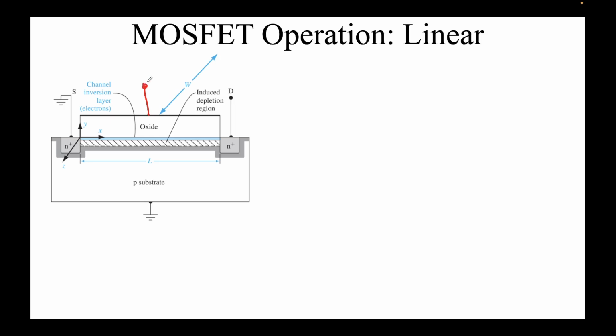The gate is over here. So the gate is modulating the field in the negative y direction. You see the y direction over here. In the gray region, what you are seeing is the depletion region. The gray color denotes the depletion, and the dashed region, this is a bit misleading. It's induced, not depletion but rather inversion, and the dashed region that you see over here is your